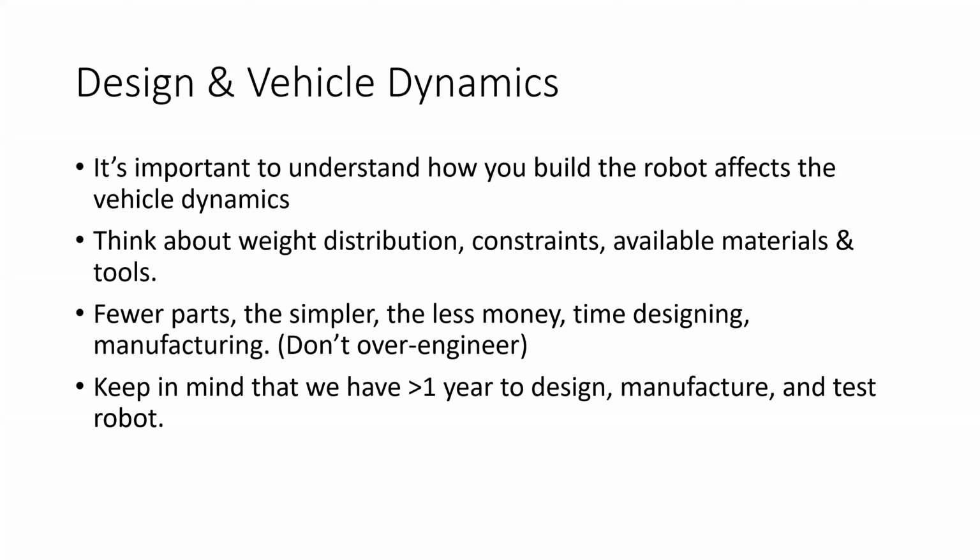Okay, so forces on wheels. Torque. What is torque? It's the rotational equivalent of linear force. Torque is equal to radius times force, as you can see in the picture on the right. So the perpendicular distance times force. With this equation, we can see that if you increase the wheel size, you actually get decreased acceleration because there's less force on the wheel.